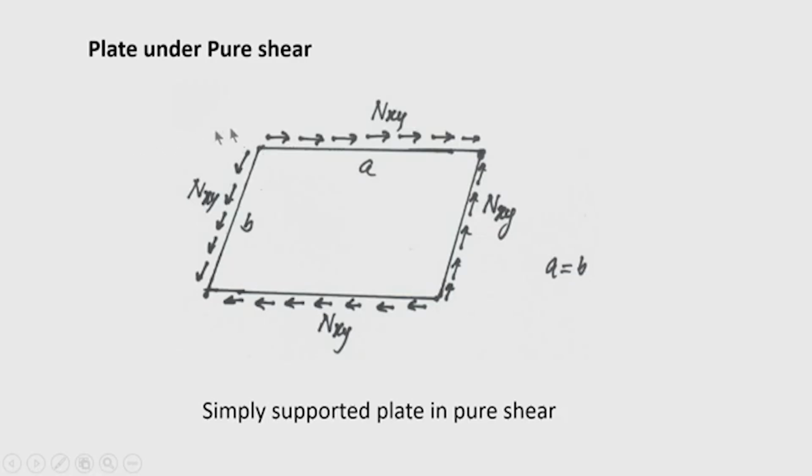Now, you can see that due to the shear acting on the element panel, diagonally it is compressed, but in the other diagonal there is a tension, and this tension sometimes reduces or minimizes the chance of buckling failure, but due to compression here there is a chance that shear buckling may take place in the panel.